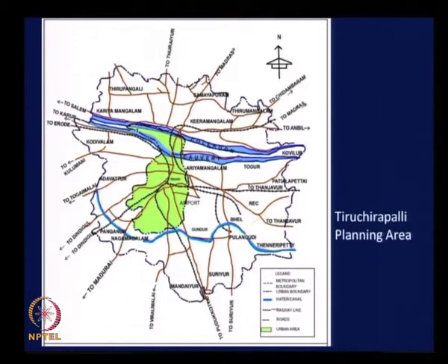That is the logic of having more traffic zones for the smaller size of the municipal area, and then fewer traffic zones elsewhere. And another important aspect is, when you divide the traffic zones, we are fixing one centroid and considering that as a trip origin and destination, isn't it? When you consider very large areas outside the municipal boundary, and fix only one point as I indicated earlier, then we will be doing a lot of approximation, representing all the trips spread over a vast area to be emanating from a single point, isn't it?